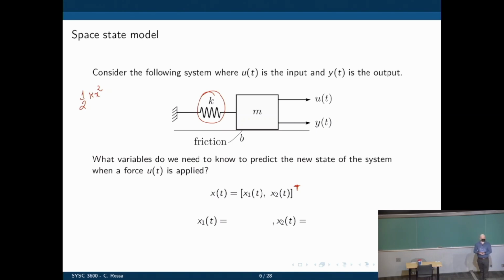Well, we have the mass itself, but it can store energy in the form of kinetic energy. And that kinetic energy is one half m y dot squared. I think I called it y, so let me just call this y and y dot squared. So I have 2 elements that can store energy. One depends on position, one depends on the speed.